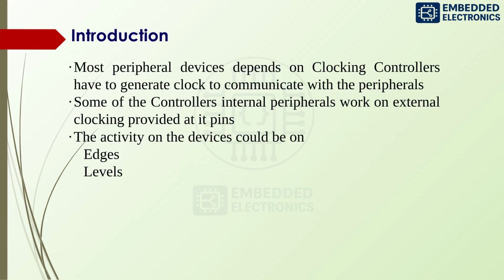Most peripheral devices depend on clocking. Controllers have to generate a clock to communicate with the peripherals. Some of the controller's internal peripherals work on external clocking provided at its pins. The activity on the devices could be on edges or levels.